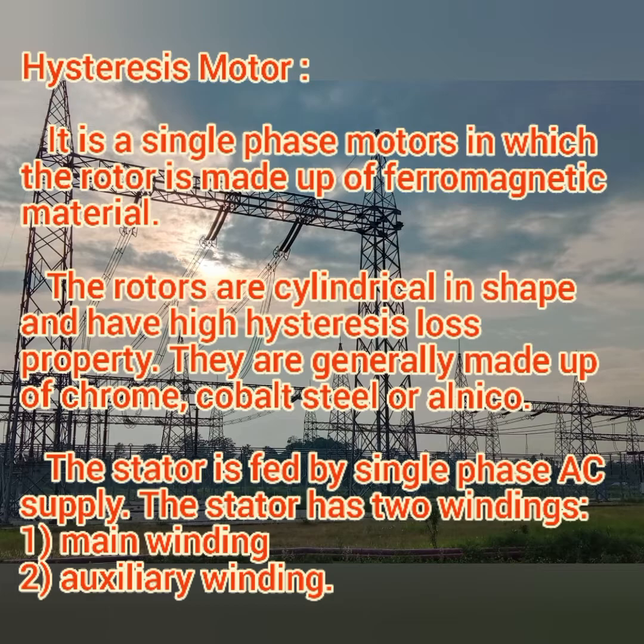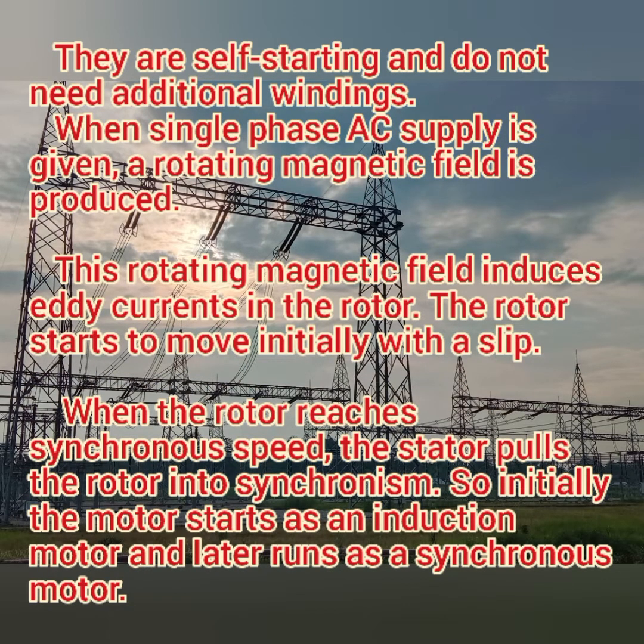The stator has two kinds of winding. One is the main winding, and the second one is the auxiliary winding. Here the hysteresis motor is not a self-starting motor and does not need any additional windings for it. When a single phase AC supply is given, a rotating magnetic field is produced, which induces eddy current in the rotor, which means circulating current inside the rotor, and the rotor starts to move initially with a slip.